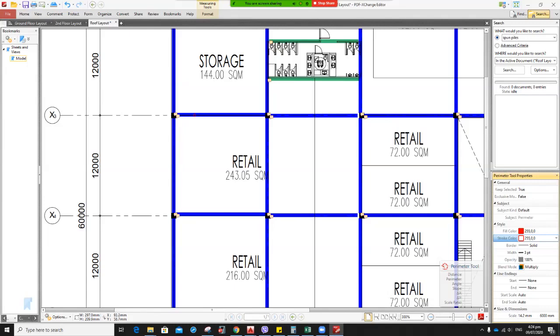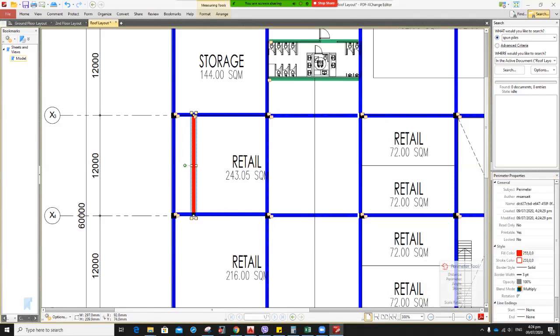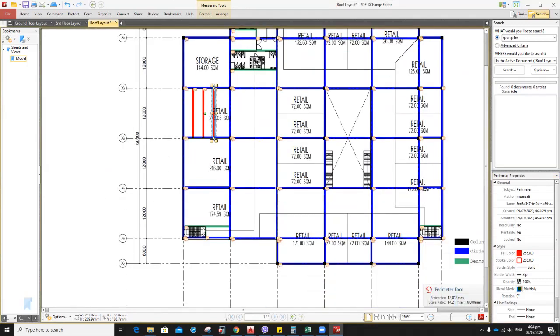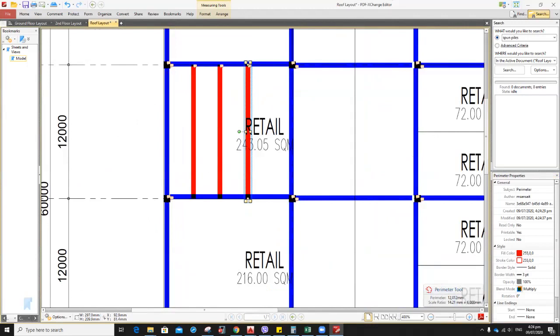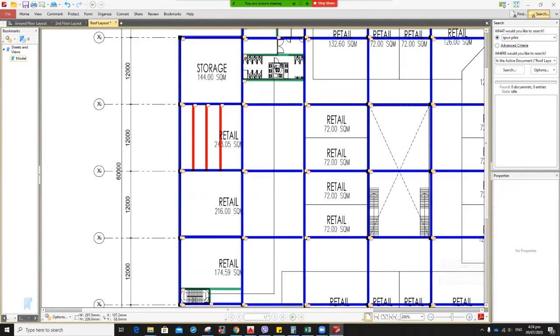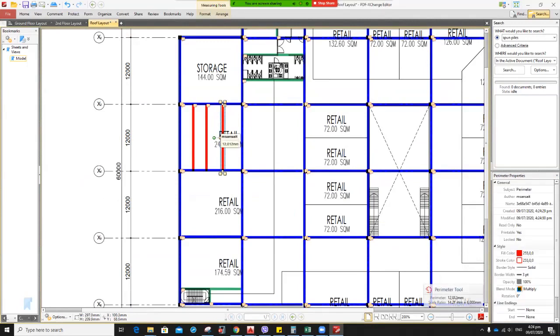So we might have trusses here, somewhere here. And just put a sample for one, so just for loading computation. We don't know yet the spacing. Maybe every 3 meters, every 6 will do. This is a 12 meter span, so every 3 meters will do. Something like that.